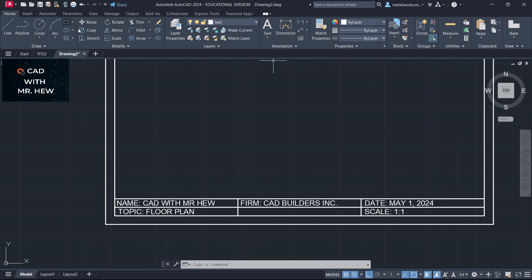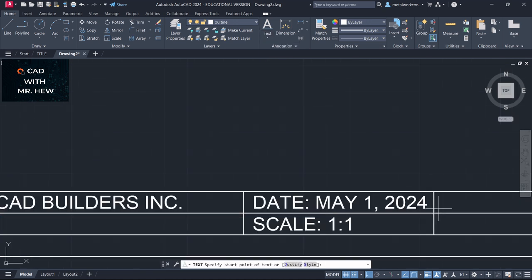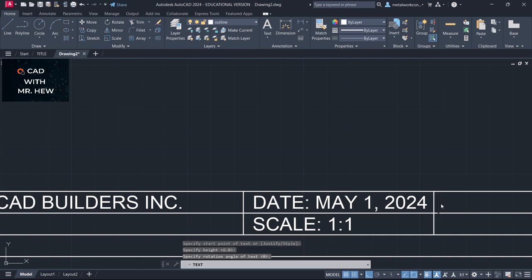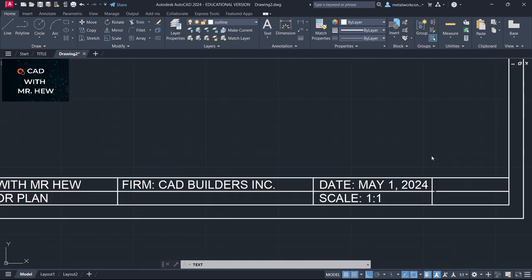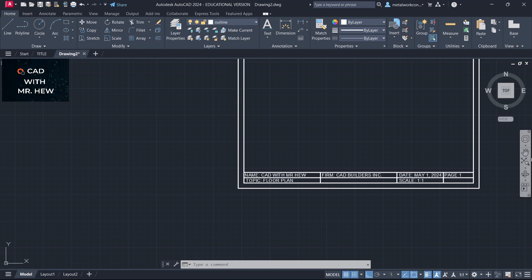You could further subdivide any of these parts if you want. So I could probably, for example, go to my outline layer, could draw another line just here. The 2 millimeter snap would pick it up and just come down. And we can probably put page numbers. So let me do that. Take single line text. Start in position. 6 millimeters rotational angle. So I could probably write page, if you need a page 1, for example. So any other information that you need, you could enter it in the title block, right? So you could further subdivide the spaces on the title block if you wanted to.